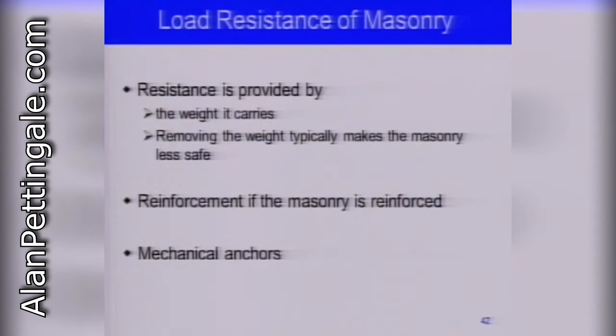If you compress it, you make it sturdier, as opposed to leaving it loose. Then it's much easier to fall apart because the arching action goes away. The shear resistance drops because resistance depends on cohesion and friction. So if you reduce the vertical load, the frictional resistance decreases as well.